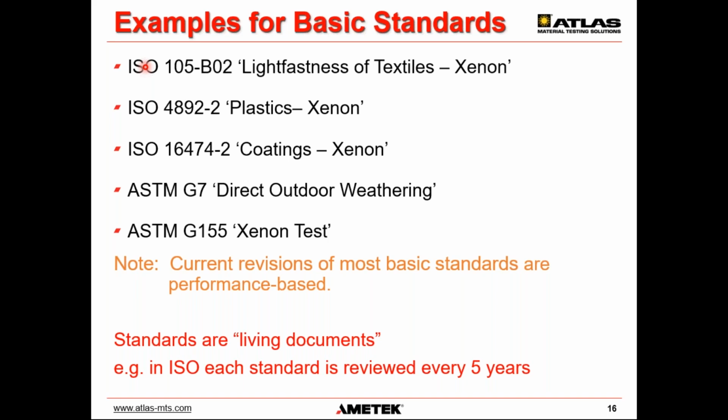This list is far from all inclusive, and there are basic standards from other weathering devices such as for carbon arc and fluorescent UV, which I didn't list here, but there are basic standards for the different weathering technologies which are used in our industry. And one thing you should note is that the general current trend is to revise and develop basic standards as performance based.